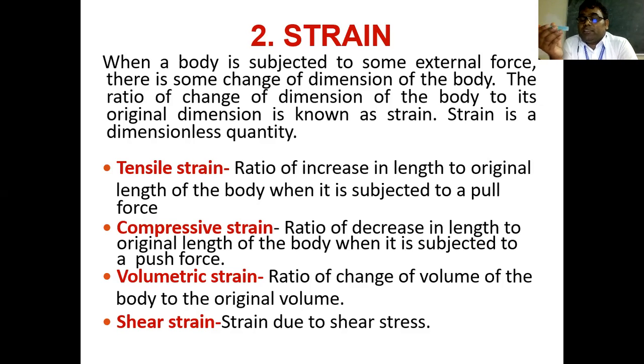So what will be the strain? What is the change that occurred? 15.35 minus 15, upon the original length, which is 15. Whatever value comes, that is called the strain. And strain is dimensionless, because both numerator and denominator are lengths, of the same unit, so both cancel and it becomes dimensionless.